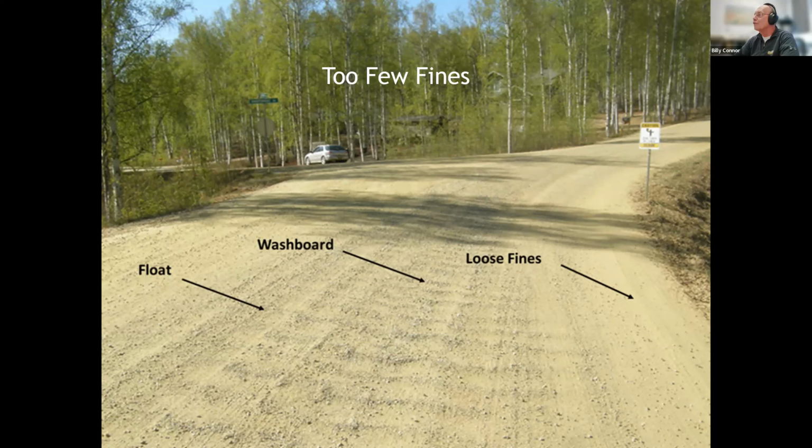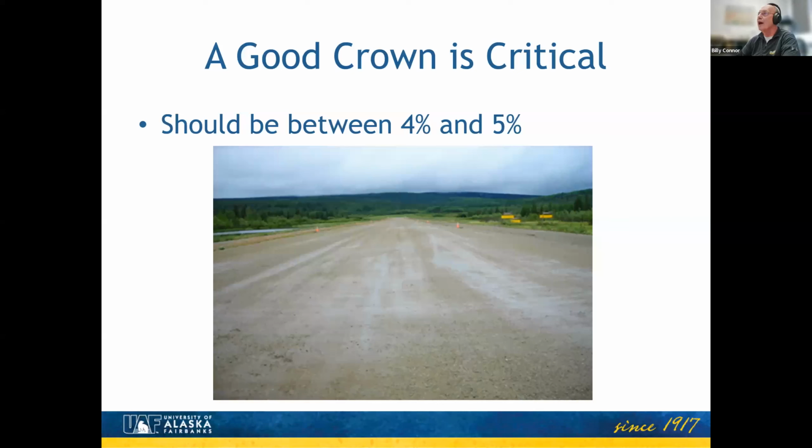And if you look over to the side, you'll see a lot of fine material being left over there, which also helps create dust. So if you see that, you really don't have enough fines in your material. And as I say, we're more than happy to work with you to get the right gradation for the material that you have. We also want to talk a little bit about the crown.